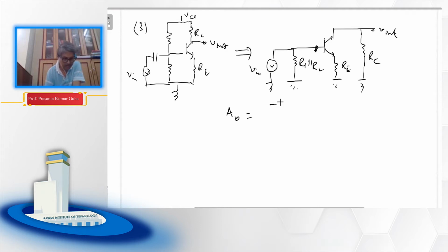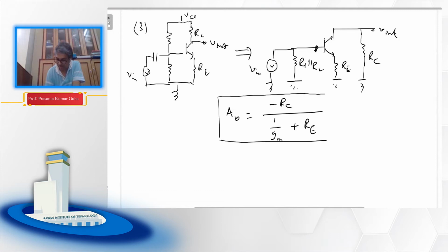However, you remember the gain we have written yesterday in this configuration is like this, because of this additional emitter degeneration resistance. The gain formula is this for this particular circuit. However, your input impedance will deteriorate because R1 R2 in parallel is again parallel to your effective (beta plus 1) RE.